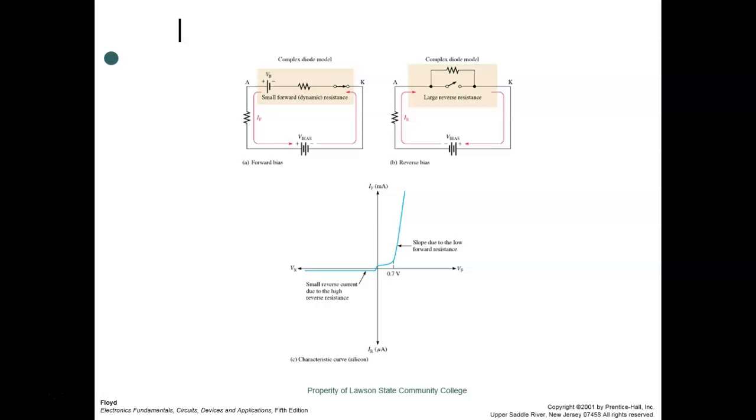After DC, guys, we don't use measured values anymore. We use color-coded values, which means all our math is going to be close, but it's not going to be exactly right, right? Y'all understand that? Everything we're going to use has a tolerance. Your diodes have a tolerance. Your transistors have a tolerance. And if you try to fool around with those tolerances, an engineer might want to do that, but we don't need it.